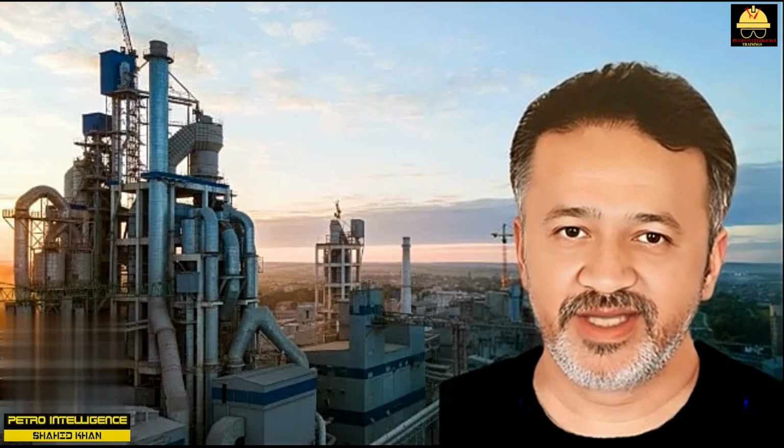The hotter, fouled tubes must grow. But their horizontal expansion is constrained by the cleaner, colder tubes. Since the colder tubes do not allow the hotter tubes to grow, the hot tubes bend. This, then, is the origin of the twisted tubes we see when an improperly designed tube bundle is pulled from its shell during a turnaround.